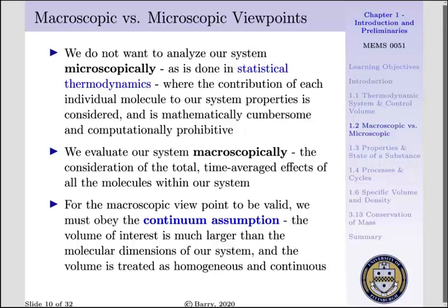We will evaluate our systems from a macroscopic viewpoint. That is, we are going to consider the total time-averaged effects of all the molecules within our system. For the macroscopic viewpoint to be valid, we must obey the continuum assumption. That is, the volume of interest is much larger than the molecular dimensions of our system. That is, the size of our system is greater than the mean free path of the molecules considered within. And in doing so, our volume is treated as homogeneous and continuous. That is, there is not a distribution of properties within our system spatially.